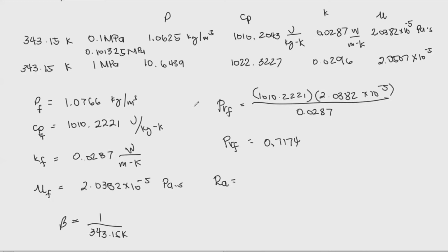But remember, when we talk about natural convection, we're more concerned about the outside environment than the fluid on the inside. Although I'm not saying that we disregard the fluid inside, the properties of the fluid that is outside of the geometry are the ones that we are focusing on for natural convection.